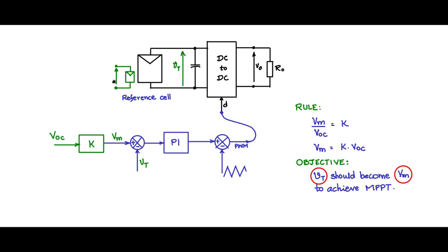The voltage across that is going to give you always open circuit value of this cell, and we will take this cell open circuit value to be same as this cell, provided this cell and this cell have the same make, same datasheet spec. So you choose the reference cell such that it is from the same manufacturer, and then use that to obtain the open circuit voltage.